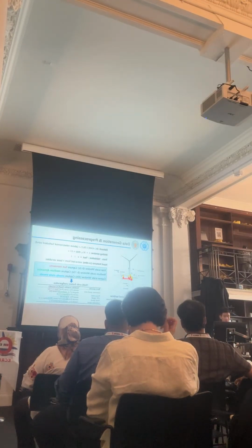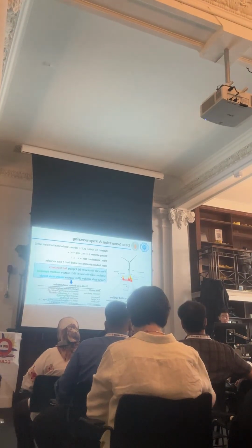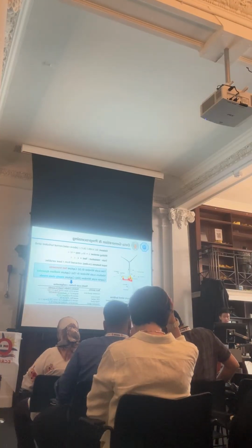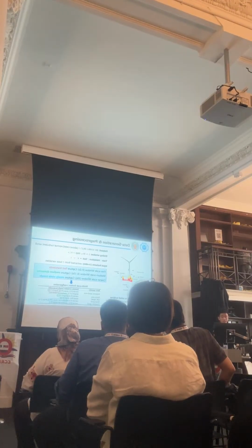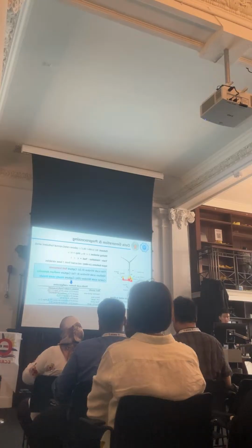We extract 14 features from the 5 base variables with 3 different window scales. The first one is the fine-scale window from 0 to 2 seconds to capture the fastest transients, like the slope of the generator speed error. The second one is the medium-scale window from 6 to 15 seconds to capture the medium dynamics, like the integral of the power error.